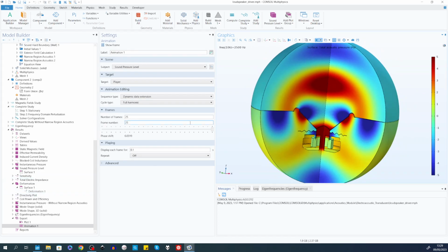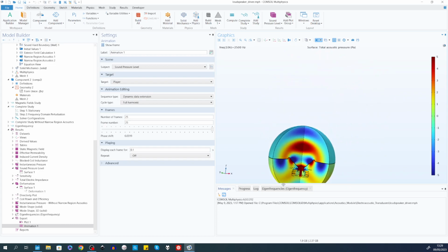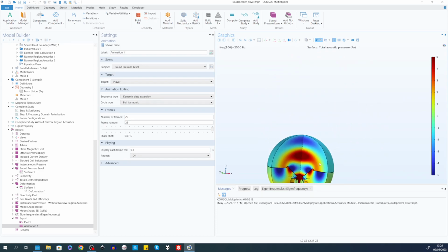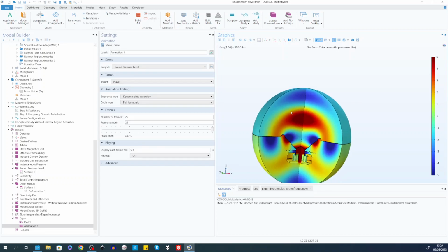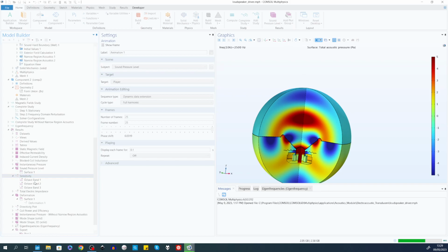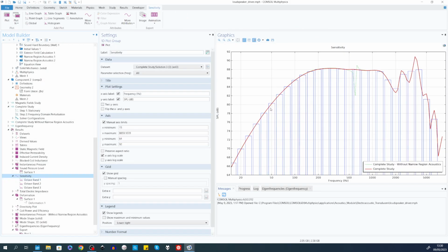And then you can say, okay, what is the sound pressure level? And you can even find it outside of this sphere here. So you can go 1 meter away, which is certainly not inside the sphere. And that's what we have here, sensitivity. And I don't even know what they have chosen, but you can visualize it in different ways. So you can see that it rolls off below 100 Hertz. It has some variations here at higher frequencies. You probably have some modal behavior going on.